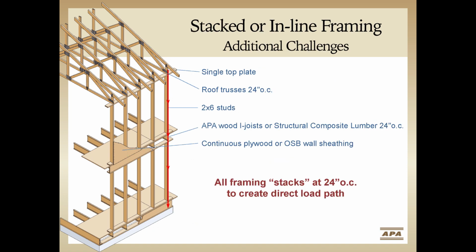One of the biggest challenges for framers is the move to stacked framing. So if we look back at this overall detail, we can see that everything is aligned at 24-inch stud spacing. Stacking your framing like this allows the option of going from a double top plate to a single, but this comes with added need for coordination. For some builders, sticking with a double top plate, which allows for random framing, may be the better option.